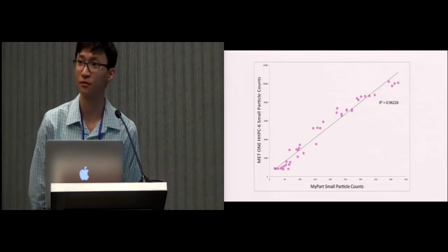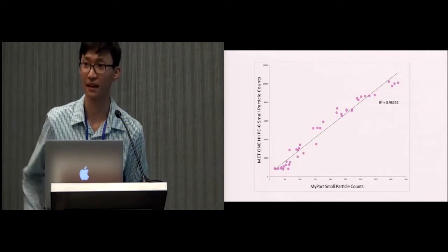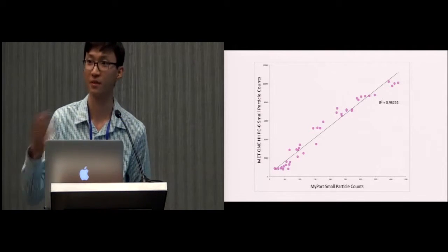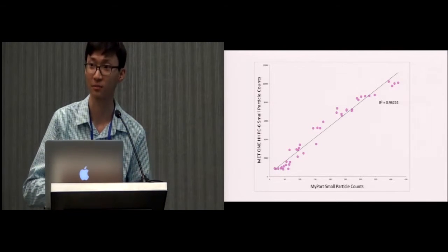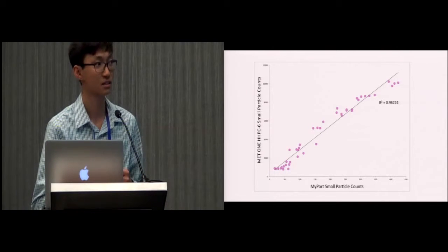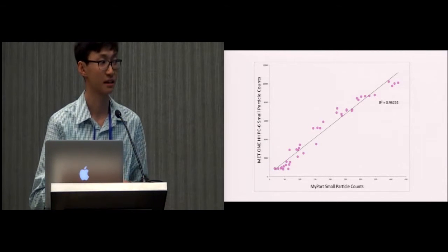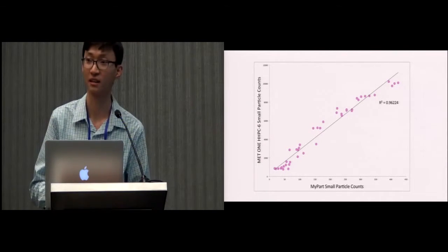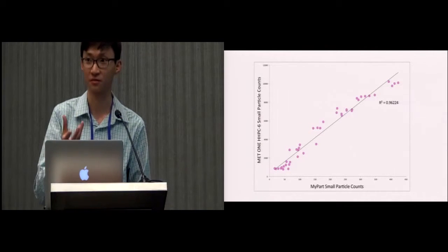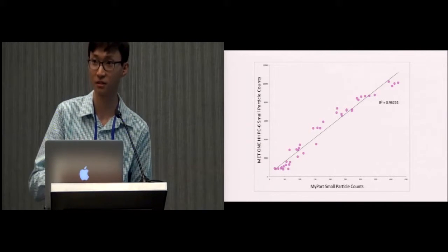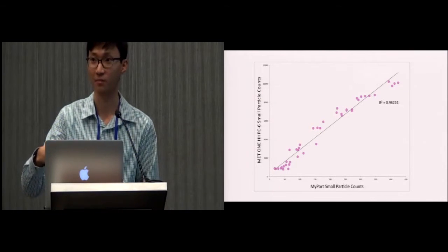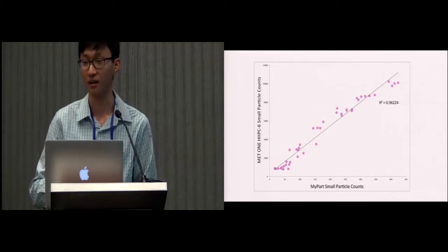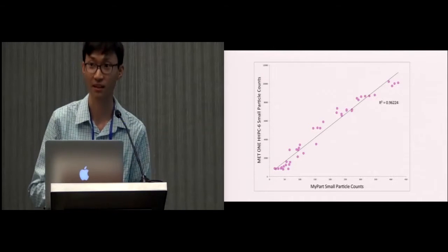I think the 400 milliamp hour battery roughly lasts a few hundred sampling cycles, and in between we drop everything, from the microcontrollers to all the different ICs, into a low power sleep mode. But the other point is that it is a totally open source design. The battery compartment was designed specifically to fit underneath at the very bottom of the device, so you can imagine having that be a trapdoor that drops into a bigger battery compartment where you can put in a much larger battery for these data logging applications.